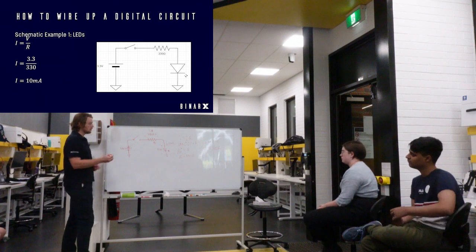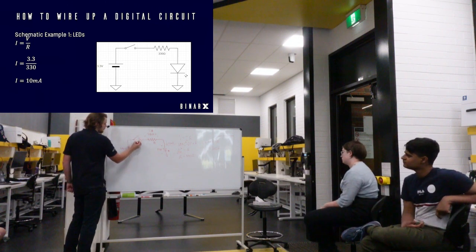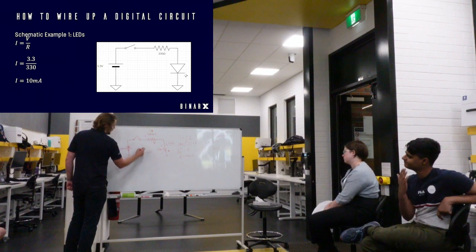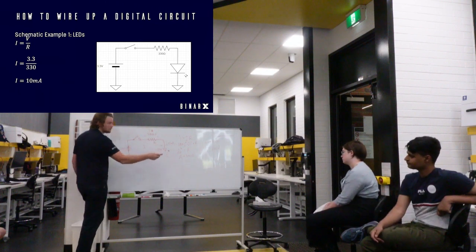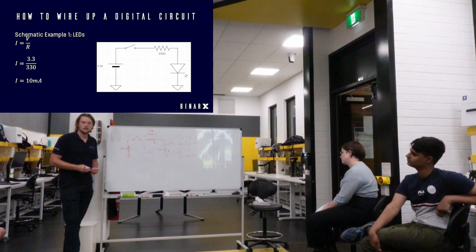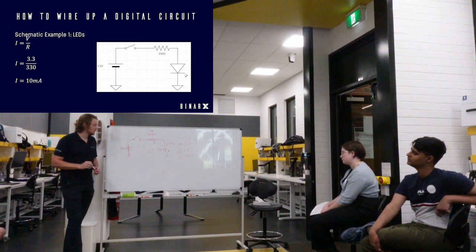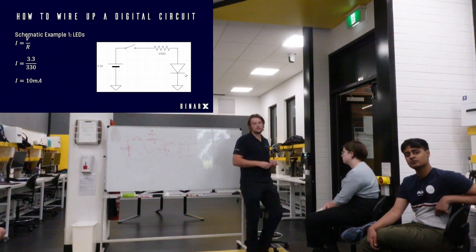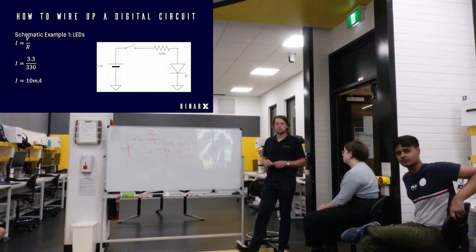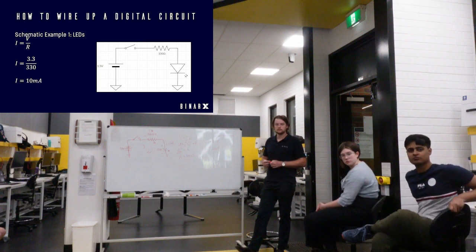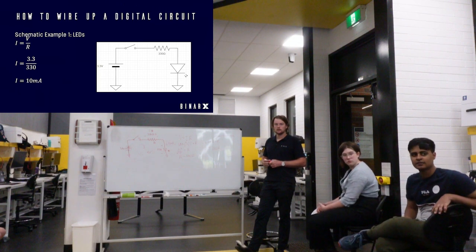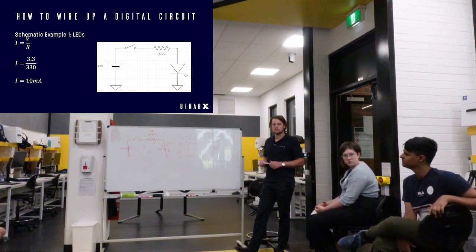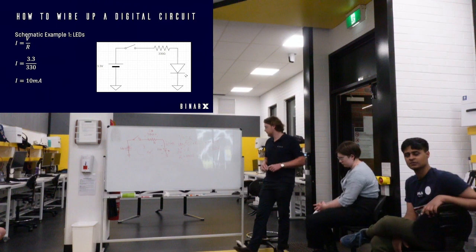So when you close this switch, the current will flow through the circuit, and then through the diode, causing it to light up. And it's okay to kind of neglect it at small voltages like 0.7, but some of our LEDs, like I think we have some white ones where the voltage drop is like 3 volts. In that case, if you calculated it for this, you'd actually need to account for the forward voltage drop, otherwise you probably wouldn't see any light.